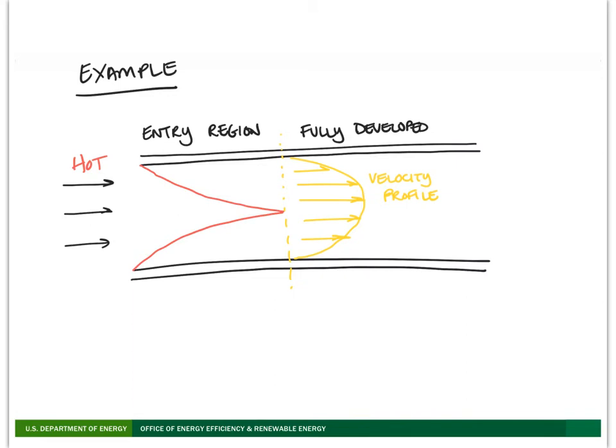In a pipe system, we associate laminar flow behavior with a lower Reynolds number, typically less than 2,300. And we can use that Reynolds number to help us determine how long the entry region might be. If we define the entry region from the start of the pipe, we will call it the hydrodynamic entry length, and we'll use x_fd,h, which is x for fully developed hydrodynamic.